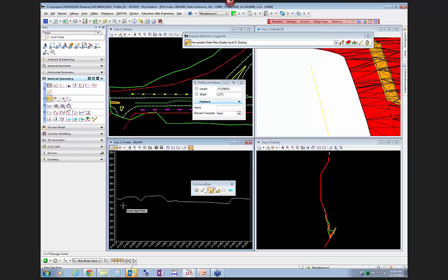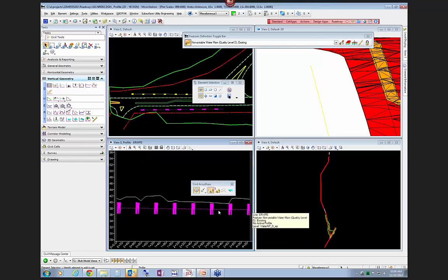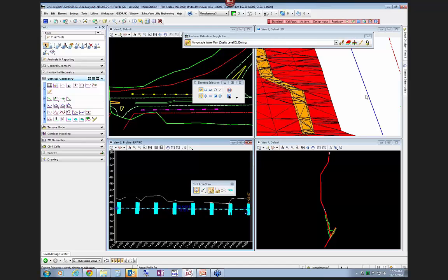And let's say I knew what this elevation was on this side, I could go ahead and toggle this on, and I could set at station 0, the elevation was supposed to be 38.1. Enter. And it places the first point. And then over here, I could do the same thing, and I'm just going to eyeball it here. And let's say I knew that elevation. And then I just click on this line again, and once I have the profile for it, if I go ahead and choose Set Active, now it draws this line out here as well.